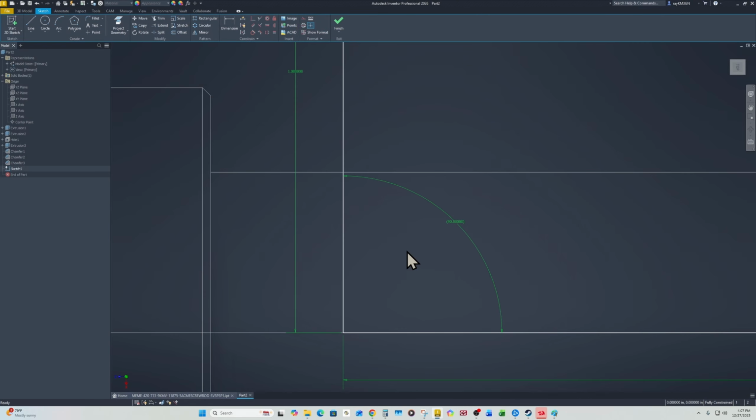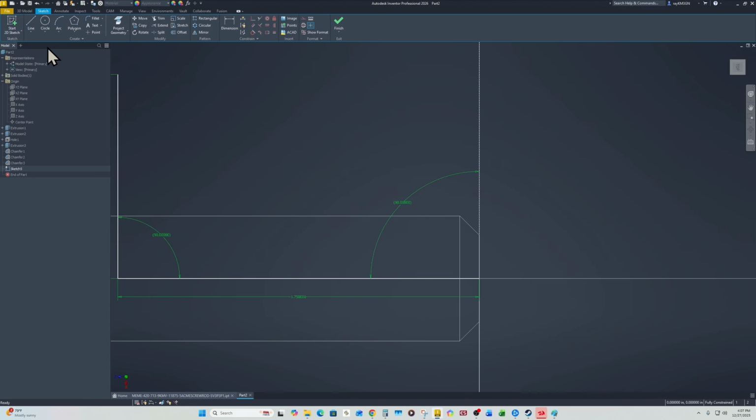Anyways, excuse me. So we're gonna do another line. We're gonna start at the middle again. Tab 0, tab 0, tab enter. We're gonna go to the right. We're gonna do 1 inch. Doesn't really matter at all. You can do 0.25, you can do 0.375, you can do 0.5. Let's just do 0.5, and then you gotta make sure it's all the way straight to the right. I think in this instance that's 90. So I'm gonna do 90, enter.